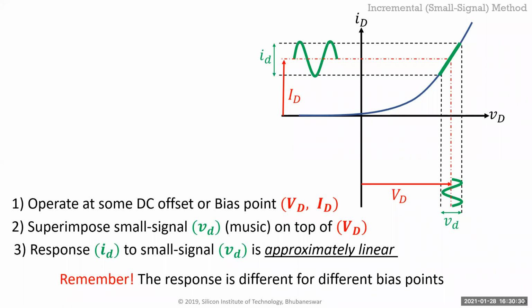So we did this calculation for the amplifier, and it turned out the gain was 40, because lambda was 0.1, which is a technology parameter, but the V effective was VDD/2 minus VTN. That's because we biased it at VDD by 2. Now let's say somehow we want to bias it at VDD by 4. Now the gain is different because I have to go back and calculate the whole thing. Well, now we have a model. We can just substitute V effective with VDD by 4 and calculate it. But you can't say the gain is 40 anymore.